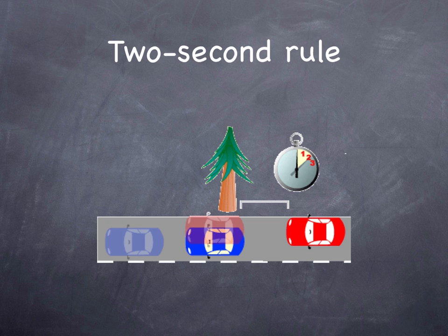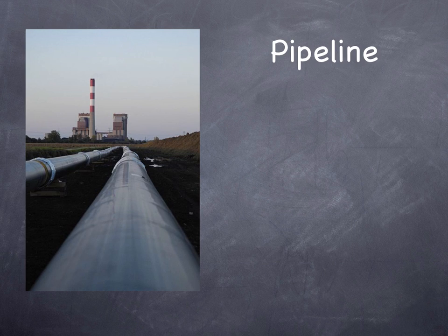3 seconds is safer. With 3 seconds, you're more likely to safely brake if the car in front of you taps their brakes than at 2 seconds, and certainly better at 2 seconds than at 1.5 seconds or 1 second. The more cars there are, the more interference you experience, and it's because they might apply their brakes and you are constrained in your actions.